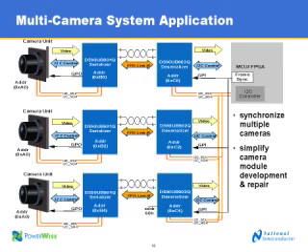I see. And then the second thing that we want to point out here is you can see these 3 GPI signals that I've identified. In this case, we've selected these, programmed these to be GPI on the deserializer and GPO, general purpose output, on the serializer. And again, this is tied in with synchronization. If there is, for instance, a frame sync pulse like we've shown here, the processor can say, here's where I'm defining my start of frame. All you cameras, I want you to align to this. So this frame sync pulse is transmitted from our deserializer over this low-speed back channel.